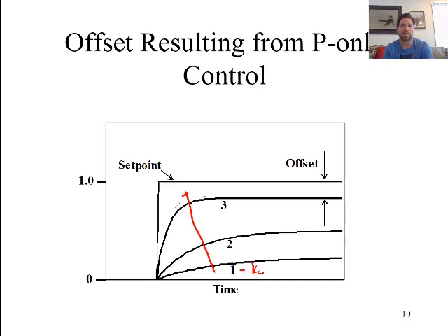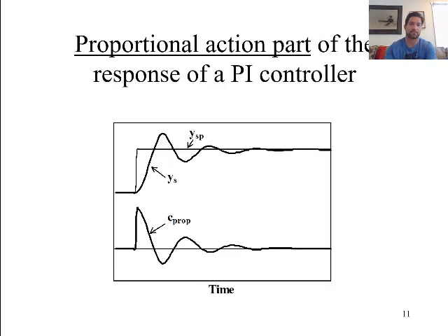So you might look at this and say, okay, on an ideal first order process, we can use a P-only controller, set the gain equal to infinity, and get a good response. Yes, that would work if it were an ideal process, but the reality is there's no such thing as an ideal first order process. Most processes are going to be higher than first order, or are going to have some dead time, and what the dead time is going to do is lead to instability. So we get this quicker response, but at some point we're going to start to add oscillations. But the point is that if you have an ideal first order process, you only need P-only with an infinite gain, but you're just not going to come across that.